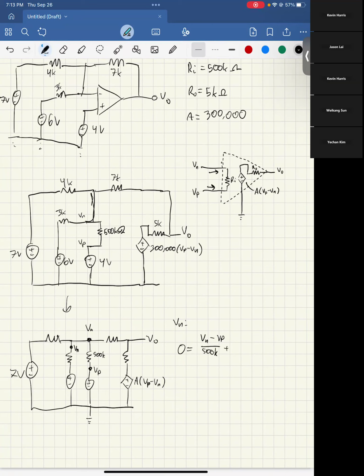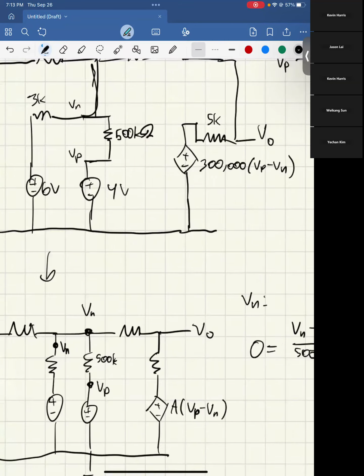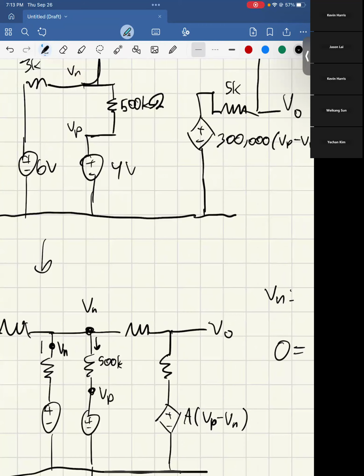You'd have Vn minus V out over, that was 7K, I think. Did I get that wrong? Oh, yeah, over 7K. Plus, again, I always like to assume that every current is going out, it just makes your numbers a lot easier.